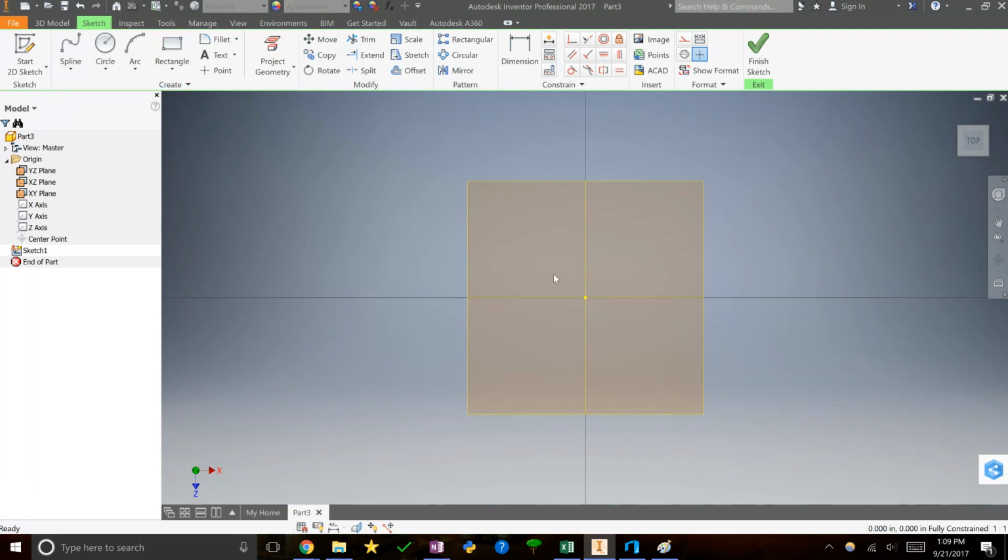In order to draw a circle in Inventor, if you look around, whoa, circle! That is so convenient. All right, so I'm going to move my little cursor here until it turns green, because that's right down the center of the z-axis. I'm going to click and drag it somewhere. When you actually do this, you should measure in your mind, take a ruler out, and figure out what actual dimension you want. This would be 1 inch in diameter. So yes, you will actually want to measure this out, but right now I'm just going to eyeball it.